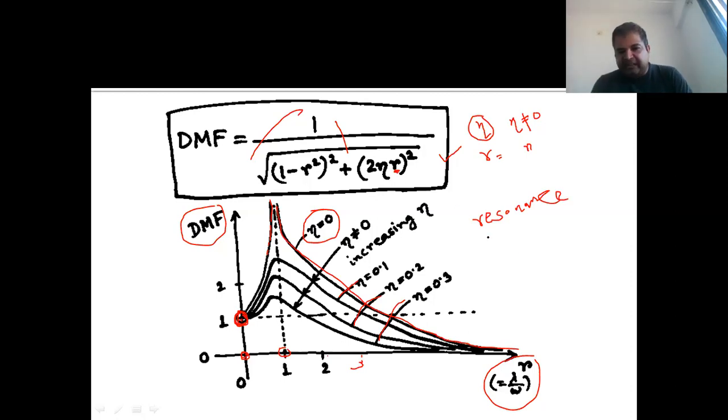So if I take the frequency ratio R, which is lambda over omega, this is your operating frequency and this is your natural frequency. When these two become equal, the ratio becomes 1. So as per our crude definition, one may say that lambda upon omega equals 1 at the point where the maximum amplitude happens. This is what is represented by this curve.